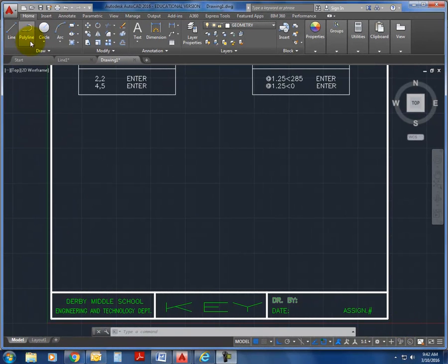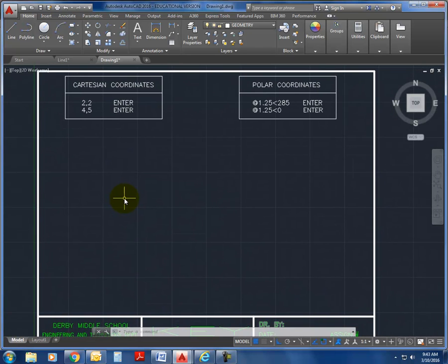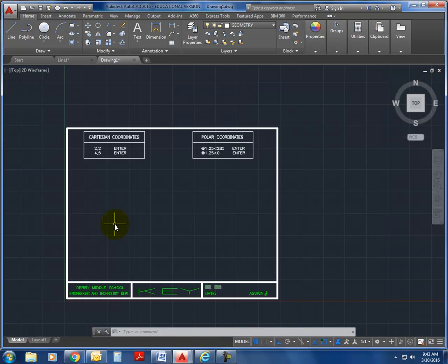Now, if you want to draw a line and you don't simply want to click anywhere and you don't want to use the grid, there are a couple of other ways to do this. If you imagine this point where this green line and this red line meet is 0, 0, this is the origin of a graph that has a grid. Well, you can start by just typing in the Cartesian coordinates. Cartesian coordinates are an XY system of coordinates.